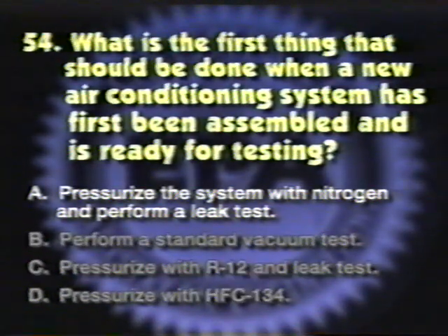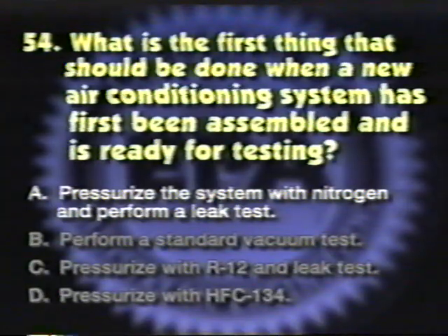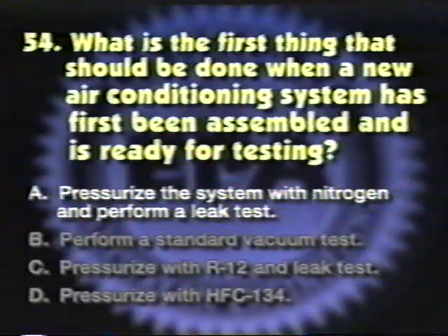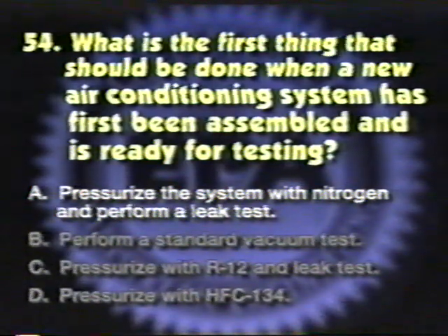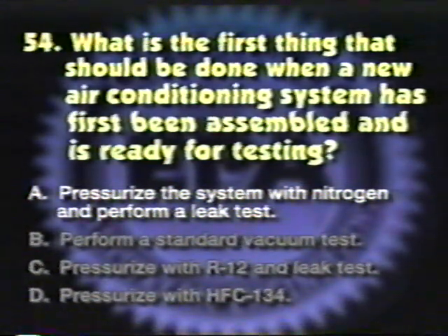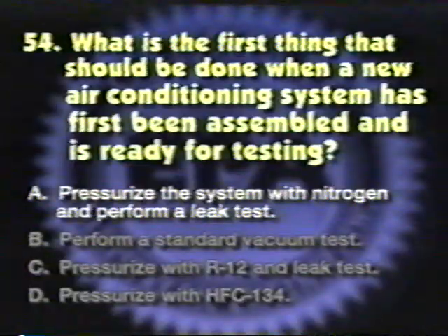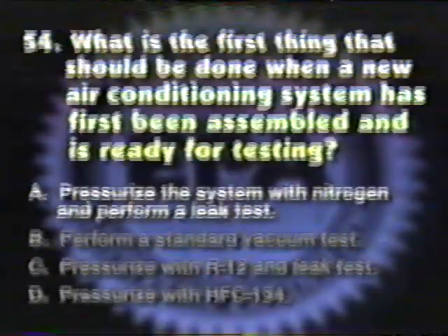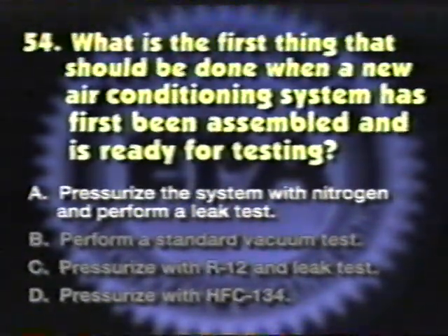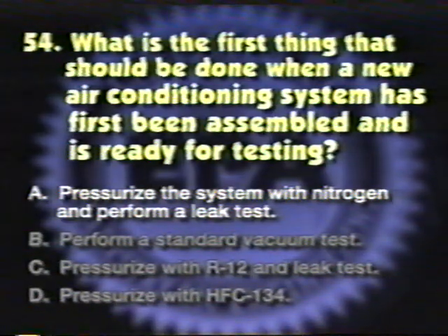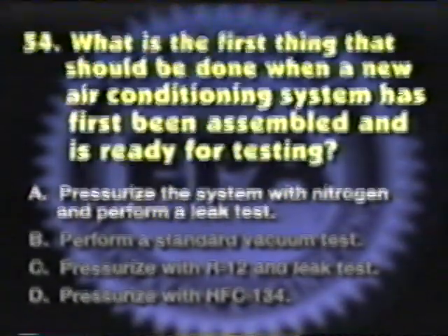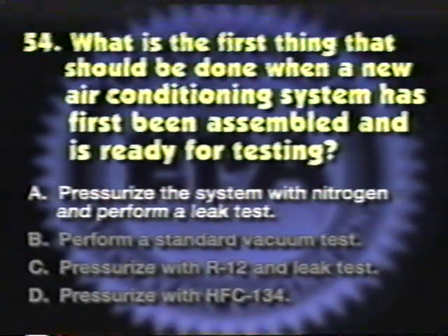The correct answer is A. When a new system has been assembled and is ready for testing, the first thing you should do is pressurize the system with an inert gas such as nitrogen and leak check the system. Positive pressure tests are more likely than vacuum tests to indicate a leak, because with a vacuum test, the maximum pressure difference is only 14.7 psi.